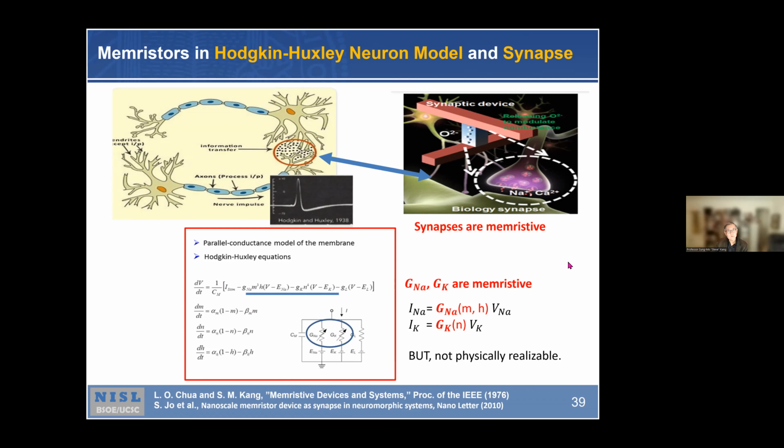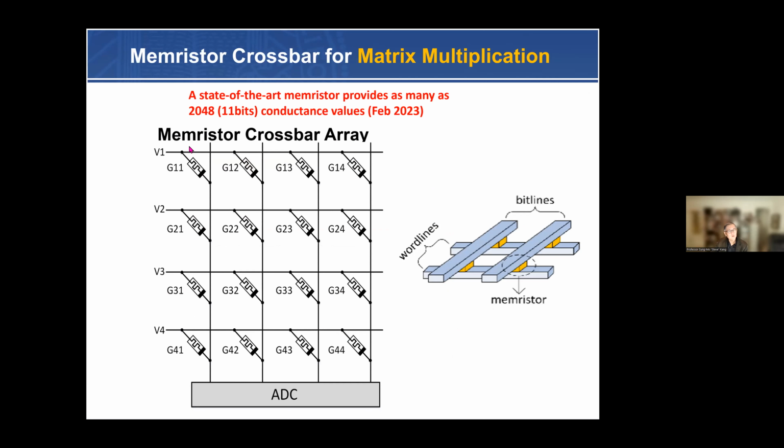This shows what is called the crossbar array. So you have a matrix structure, and in between you put memristors. By applying voltage biasing, you can program all these different weights. This shows some matrix structure of this device, the crossbar array.